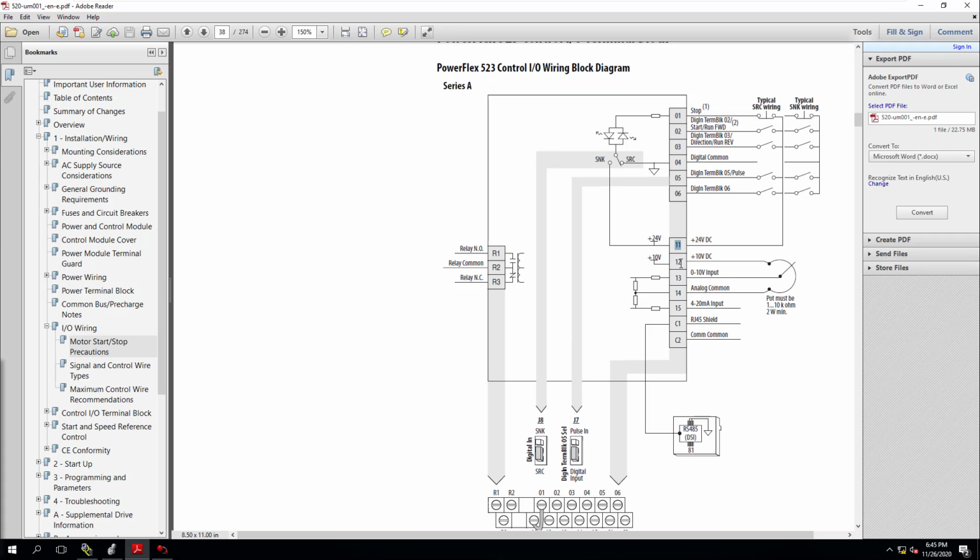to one side of the normally open contact on that ice cube relay, and then you would wire the other side, in our instance of the training, to digital input 2, which is what we're using to transition our actual step logic. So in our instance of using the step logic, we used digital 2 and we used the 24 volt. I'm taking that through a switch, just a normally open push button, and I'm pushing the button every time I want to change states.